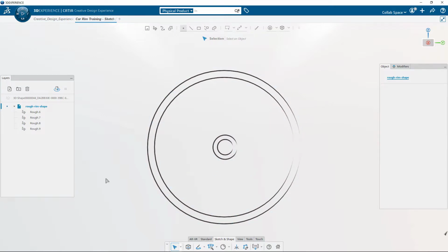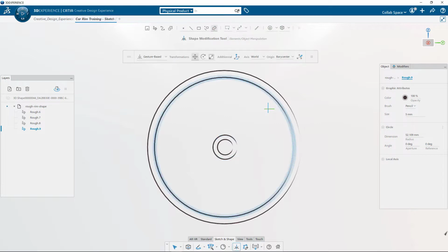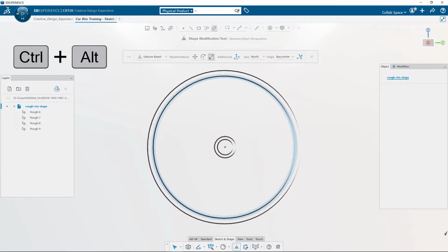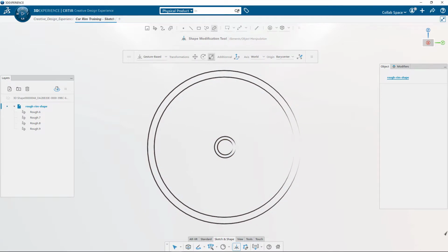I then use the transform command in the action bar to start repositioning or editing the circle. I switch to object selection filter in the option bar and start with the scaling transformation mode in the toolbar. With the implicit selection, I scale down the circle with Ctrl and Alt pressed. And I don't even have to select the circle itself, just to make sure it is pre-highlighted.